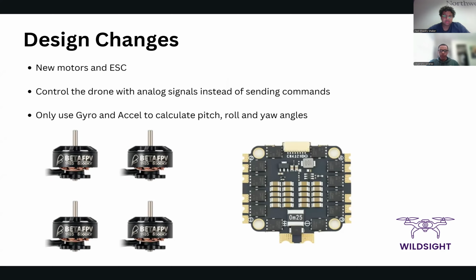In terms of the control for the drone, we originally had a little arrow keypad that you would press to send a signal of up, down, left, and right for the drone. But we found that in order to make a more effective control system, we're planning to have an analog joystick instead that sends roll, pitch, and yaw data to our controller, and that will determine how much our drone actually tilts and moves forward.